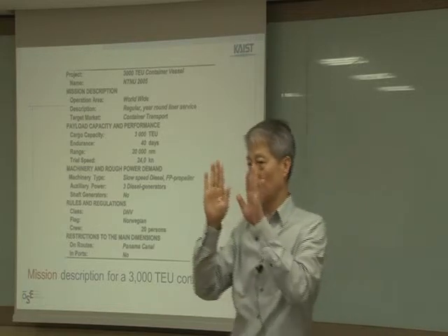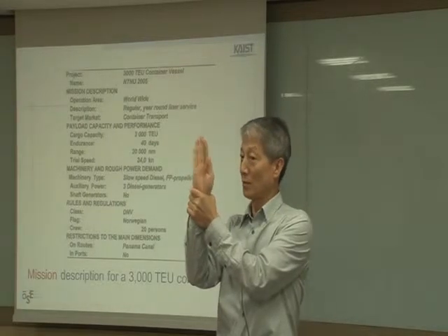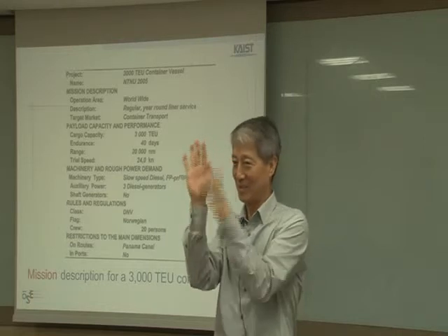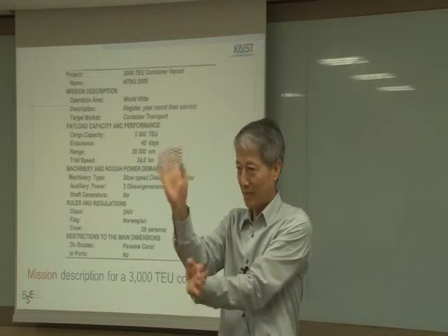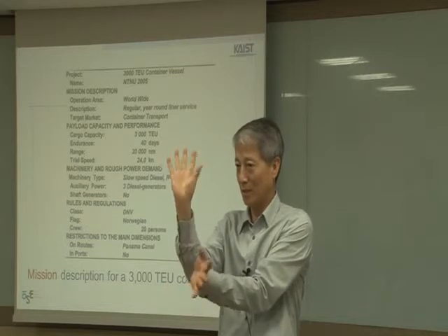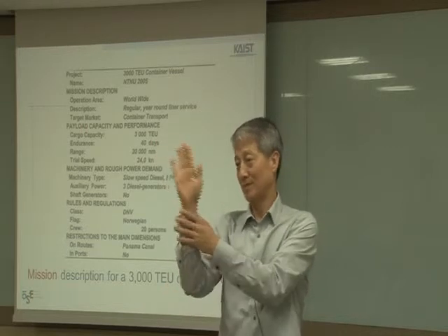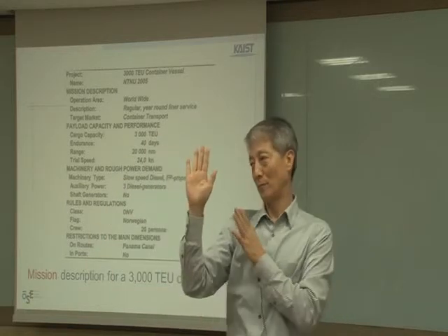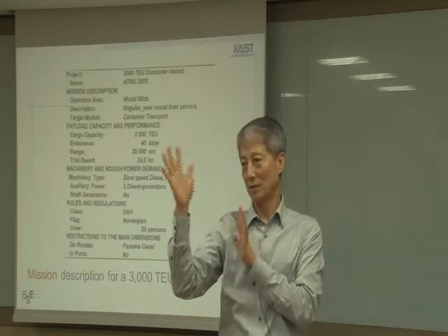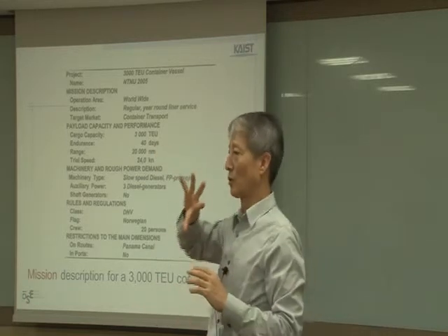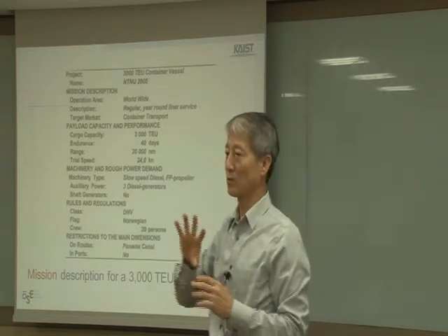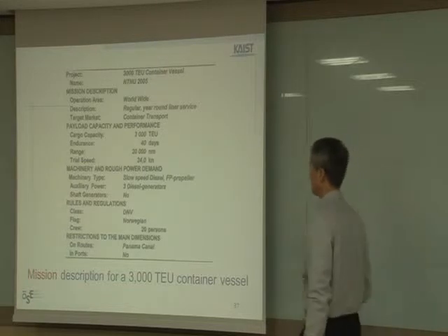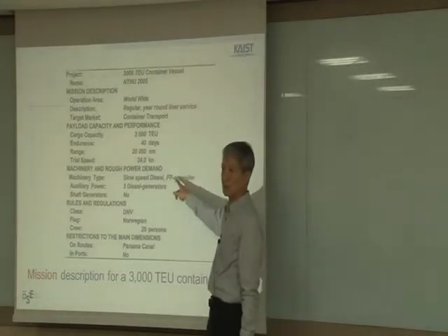But sometimes there is a propeller which can rotate the blade, not the whole unit. We have 3 or 4 blades, but each can be rotated so that they can change pitch. Pitch is the angle of the surface, right? By rotating, we can change the pitch so that one rotation gives more advance or less advance. So we call this a controllable pitch propeller, compared to the fixed pitch.